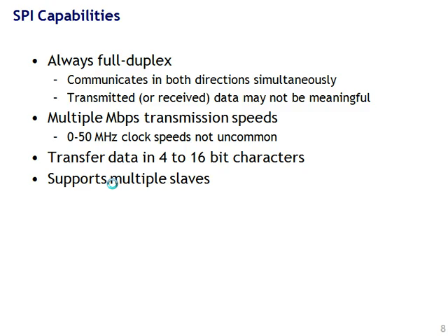Anything you may have seen that has half duplex? How about MIDI? Anybody ever hear of a MIDI synthesizer? MIDI synthesizers are keyboards. They have 5-pin interfaces. They call them circular DIN keyboards, and that's a simplex local area network connector. Each one has an input and each one has an output, and you daisy chain these things together. It's very good for consumer electronics. Very low data rate, 38 kilobits per second, but just fine for keyboard inputs and outputs. And normally the command is key on, key off, and a key number.